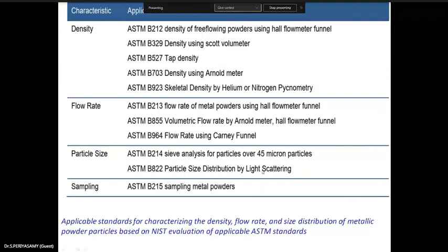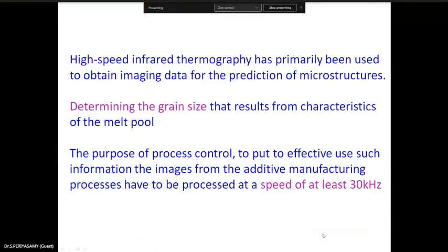The defects will lead to failure at some point, and finding them is also very difficult. In a normal conventional material, you can easily cut it and find the defects. Sometimes in a spare piece you can find defects. While cutting the mild steel, you can find some voids or flaws inside. But if you are manufacturing the same part by additive manufacturing, it's very difficult to find them.